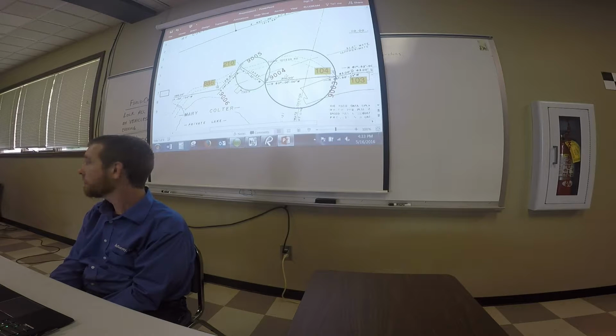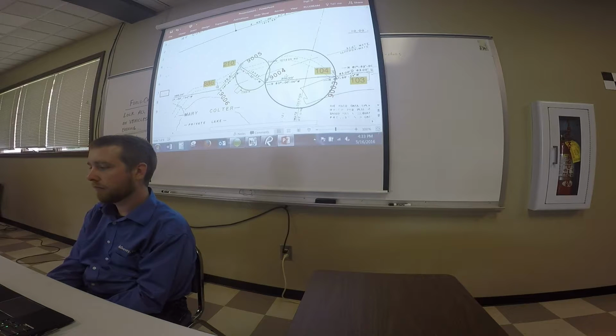So that 2/10 is hitting somewhere on top of a 4-inch concrete monument. And you know that in the field before we know it. So if you go, okay, I got a 1/2-inch rebar back here at 210, and I got a concrete monument at 104, hold that 1/2-inch rebar and turn your angles and distances and put that sucker in, because you're still going to hit that concrete monument on that 2/10 off.